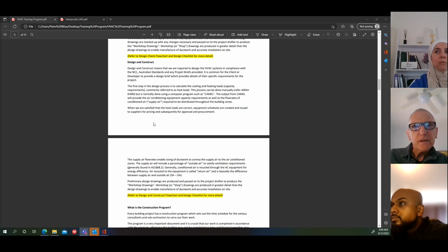If you look at those, you can get a pretty quick idea of whether the answer is right or wrong. So for a typical building, your heat load might turn out to be, let's say, 120 watts a square metre. And if you get that answer, you've probably got the right answer. If you get an answer like 1,000 watts a square metre, there's something wrong.